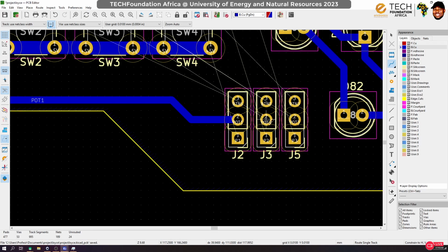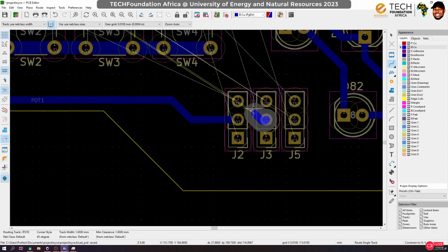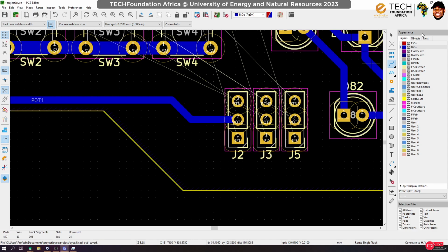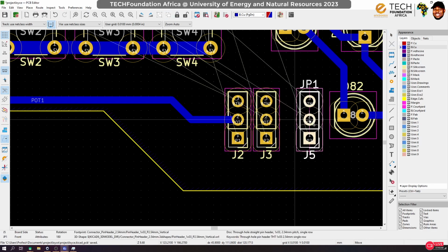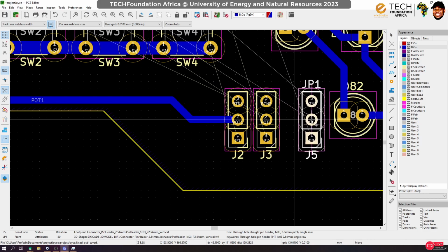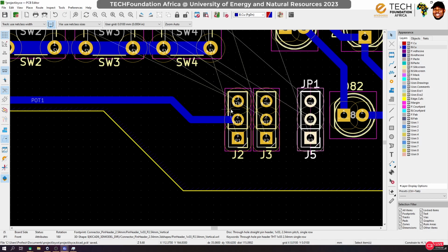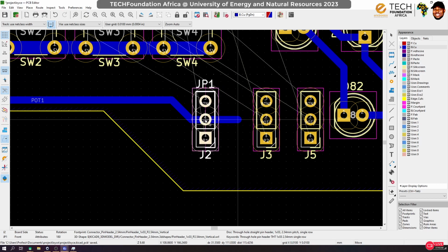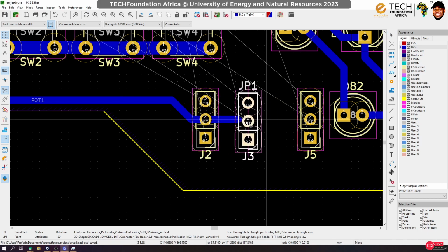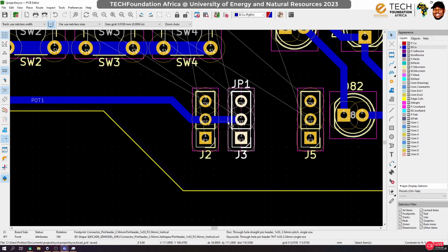If all were to be this easy. Exactly. So yes, we may have to resort to putting spaces in between. Now, if we were routing for a professional PCB house, this wouldn't have been a problem because in that case, I could make the traces thinner.